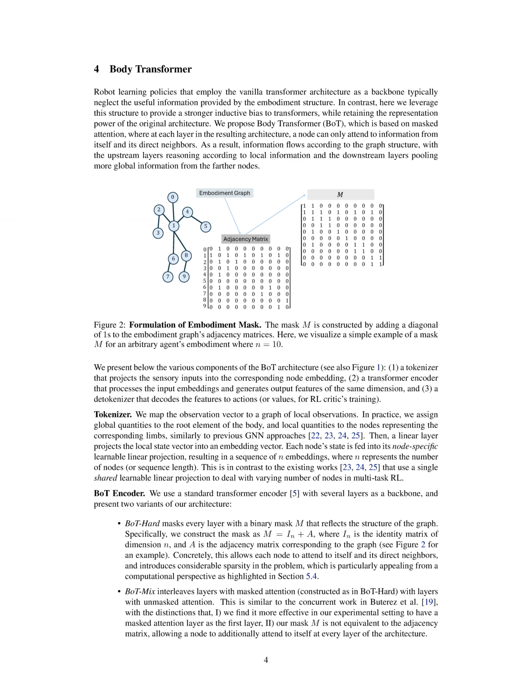The body transformer, BOT architecture processes sensory inputs through a structured pipeline involving a tokenizer and a detokenizer. For instance, when a robot receives sensory data, the tokenizer maps this observation vector into a graph representation where each node corresponds to a specific sensor or actuator on the robot's body. This mapping assigns global quantities to the root node and local quantities to the limb nodes, followed by a linear projection that generates node-specific embeddings.